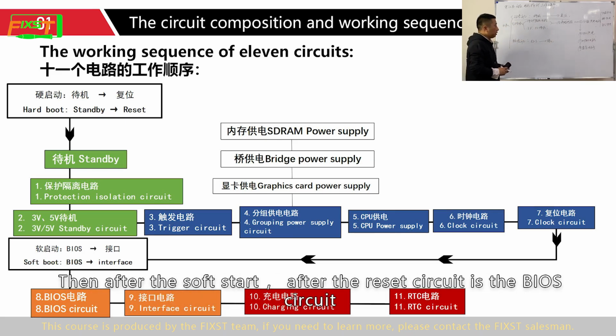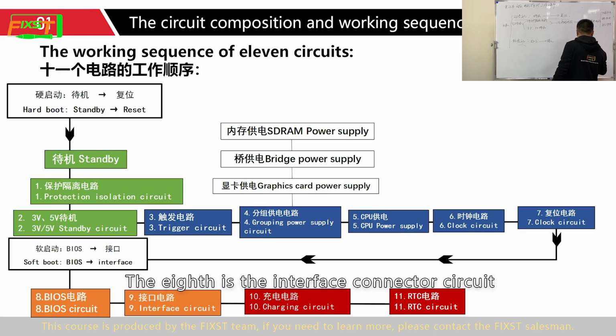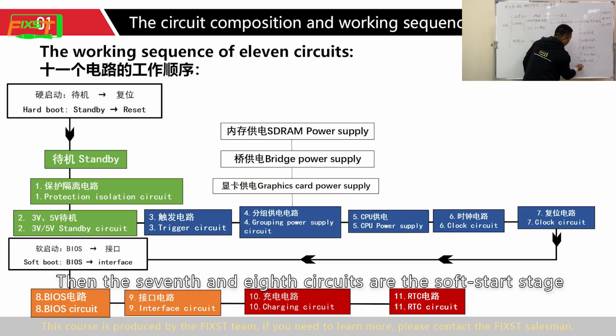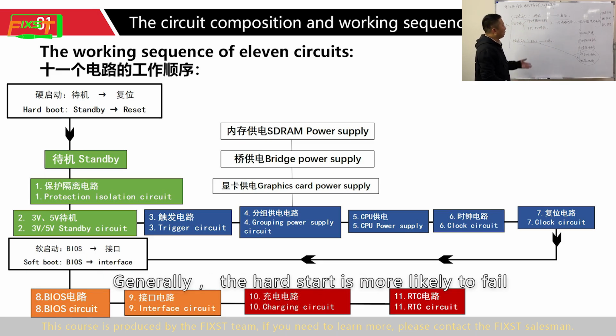Then the soft start comes after the reset circuit. The seventh is the BIOS circuit. The eighth is the interface connector circuit. Circuits 7 and 8 are the soft start stage. The first 6 circuits belong to the hard start phase. Generally, the hard start is more likely to fail.